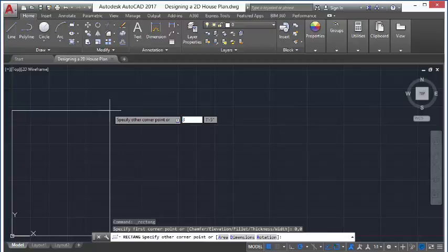Now, if I enter 30, then I press comma, AutoCAD interprets this to be 2 feet 6. When you divide the 30 inches by 12, the answer is 2.5. So AutoCAD does the calculation and interprets the 30 inches as 2 feet 6. So how do you tell AutoCAD that you want to enter feet?